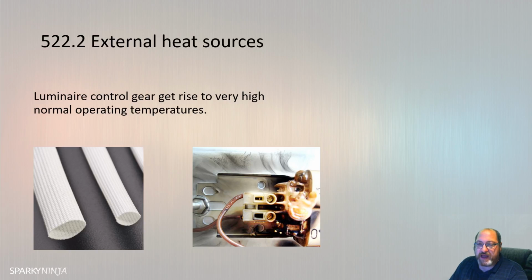Or you may have a luminaire with, if you still work with these days, a ballast in there, and there'll be a metal shield in there, and you run the cables the other side, especially with through wiring. So the manufacturers do accommodate heating effect. They do find ways for us to install them. If we install to the manufacturers' instructions, then there shouldn't be a problem.